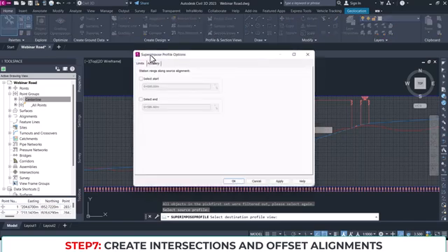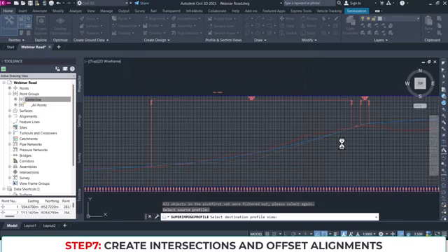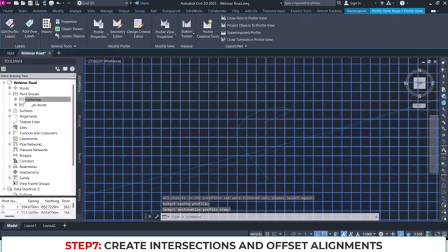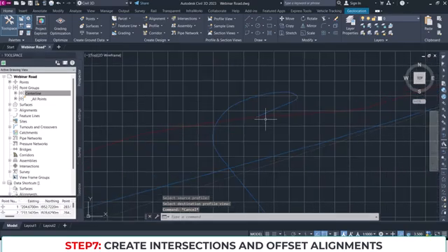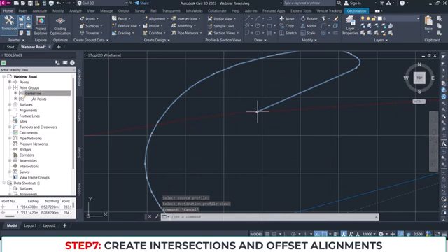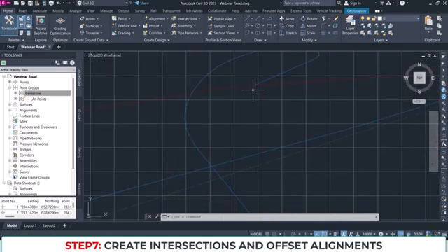It opens up this ribbon and allows you to select whatever you want to select here. I won't go through all these things, but if you want only some sections shown, you can choose. I want everything shown, so let me just press apply, and press OK. So now you can see how road 2 is on road 1. Obviously the levels are different. See where this one is intersecting. So these two levels have to be married.